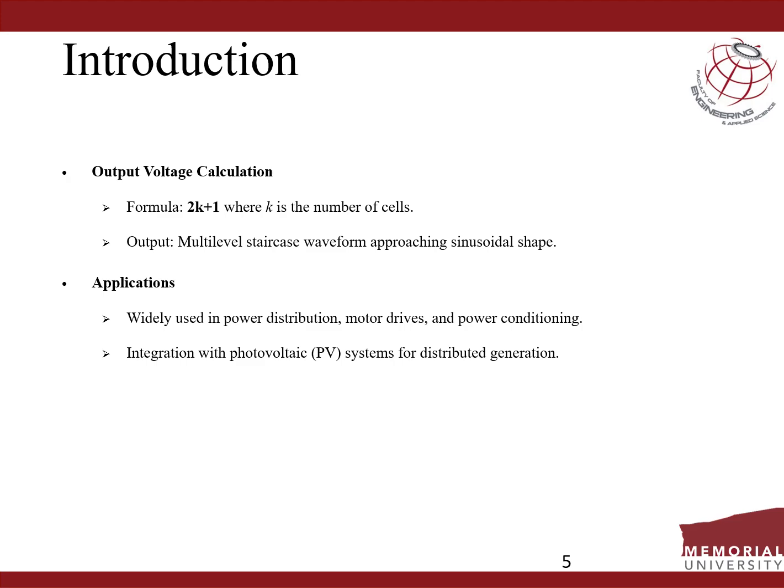And for the output voltage calculation, we use the formula 2k plus 1, where k is the number of cells. And if we observe the output waveform, it is a multi-level staircase waveform, which approaches the sinusoidal shape. And I have also discussed the applications of the multi-level inverter.